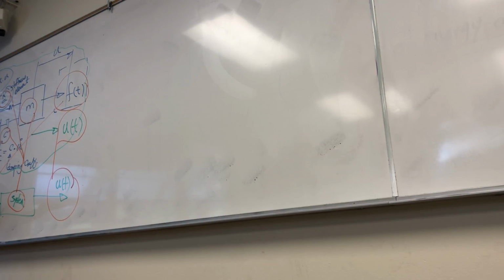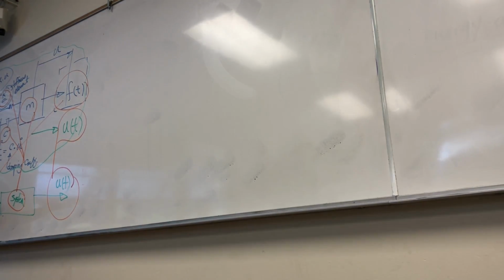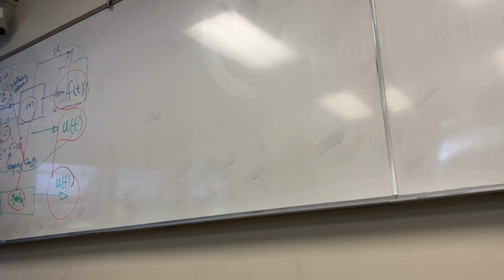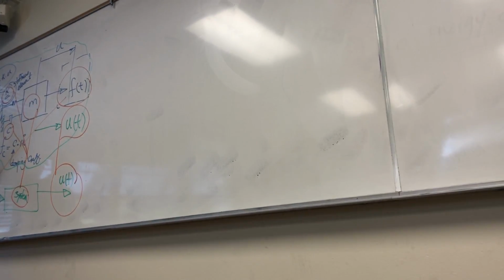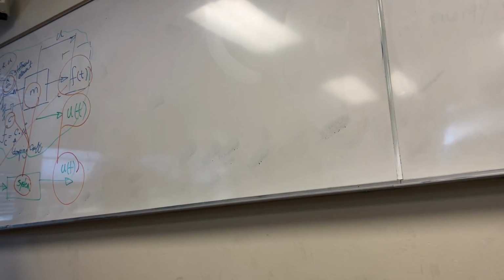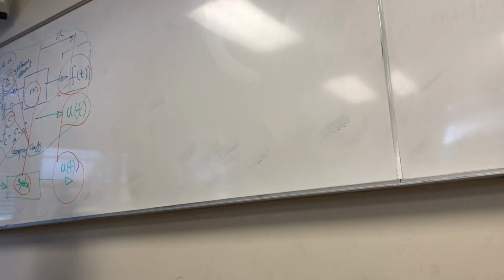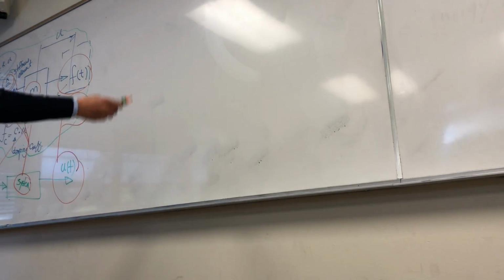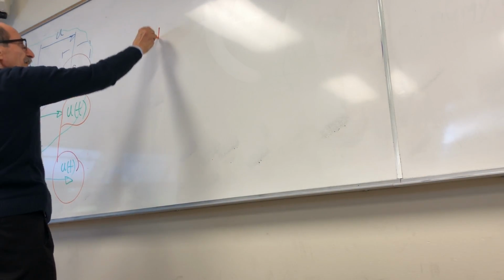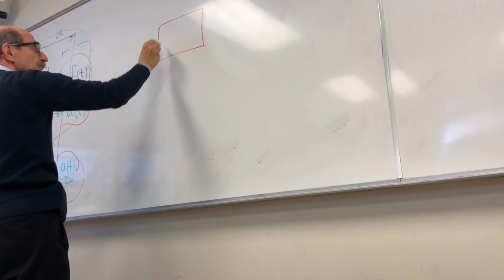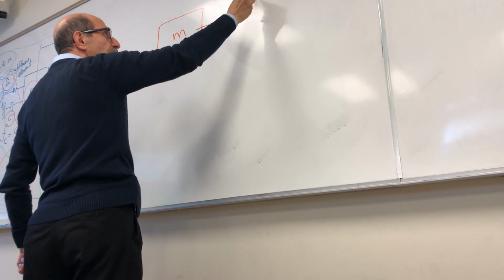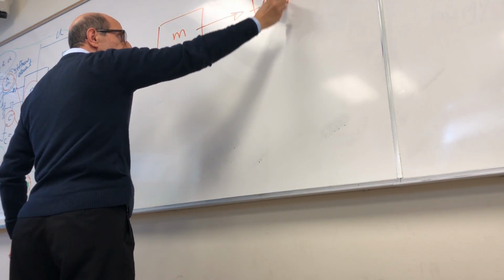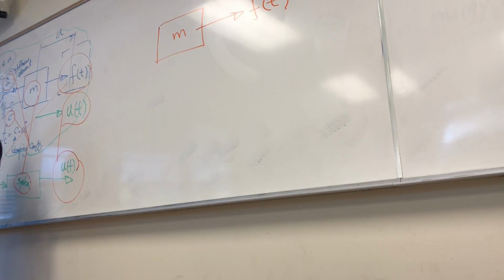I emphasize in my course that it's 85% of statics: the free body diagram. That's what we're going to do to study this creature now. That's what you did in dynamics too, I assume. What does that mean? You have a system that is going through the action of an external force. That's one force. You free it from all the constraints.